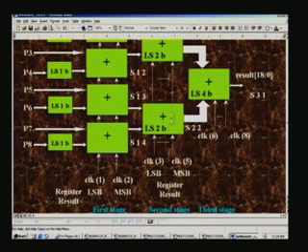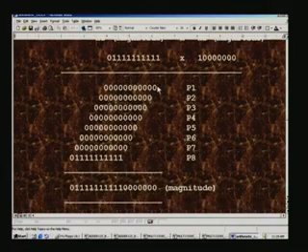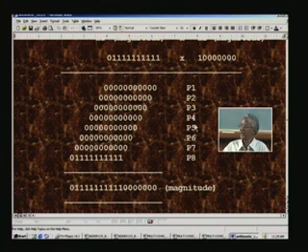So we will explain why these 2 bits here. What we are doing is taking the sum of the first stage. If you look at this example once again, we are adding this, and out comes the result here, and we are adding this, and there will be a result here. Those 2 results we are trying to add. So naturally the first result is taken as such, whereas the second result is shifted by 2 bits, because if you see the second group, it is shifted by 2 bits from the first group. This is the first one, and the corresponding first partial product is this one. Therefore there is a shift of 2 here. Therefore the second stage of addition will have 2 shifts.